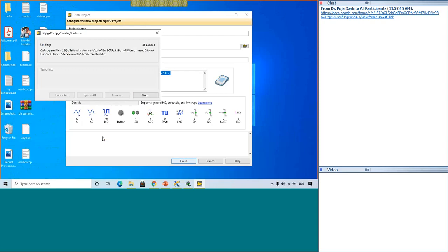So even though we have specific hardware for acquiring the data, you could see that your Rio also has 12 analog inputs. But the specifications are very clear: it could read only up to plus or minus 10 volts. But realistically speaking, our voltage will be in terms of 400 volt RMS or in the kilovolt range.